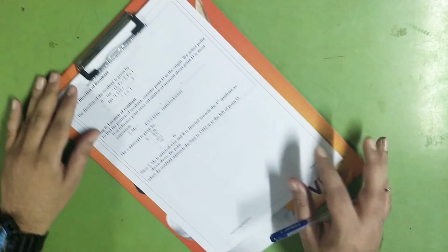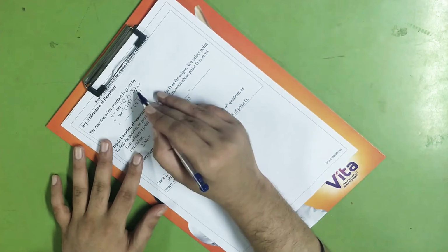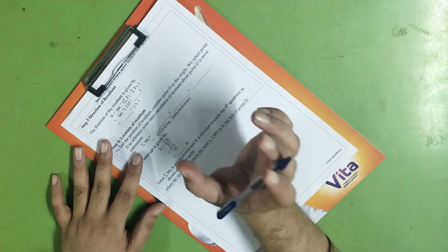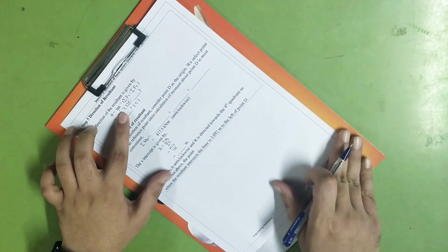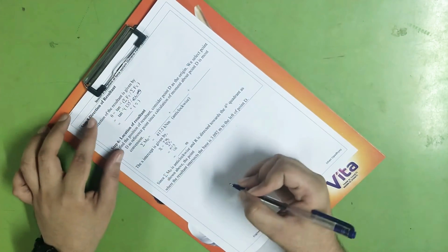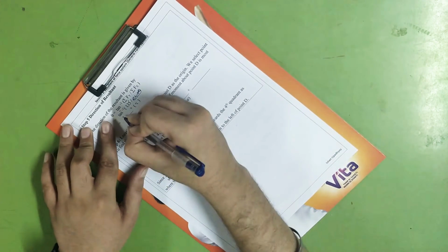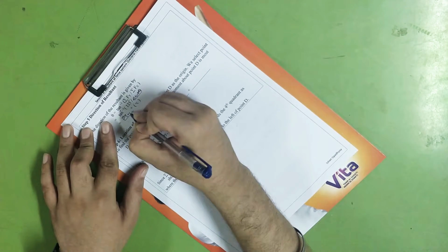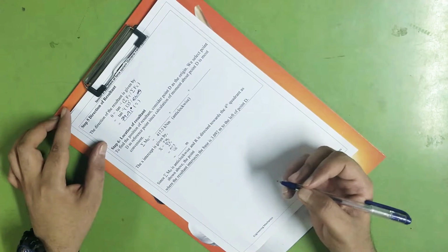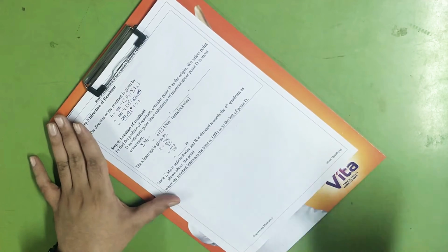Next we will go for the direction of the resultant. So we have to find the angle theta. The formula for angle theta is tan inverse of summation of Fy by Fx. Remember, for this we will consider Fy and Fx only as positive values. Fy is 135 and Fx we know is 24.02. On solving, tan inverse of 135 by 24.02 will give you the answer as 79.91 degrees. So the resultant is acting at 79.91 degrees.